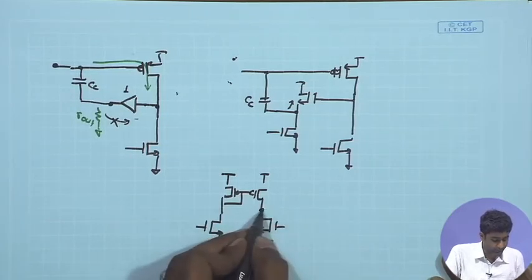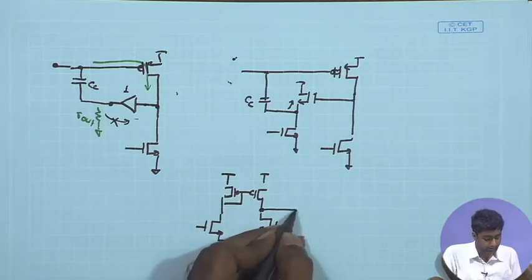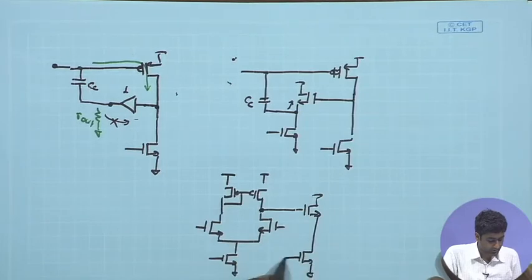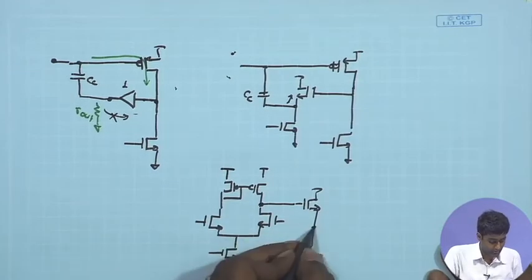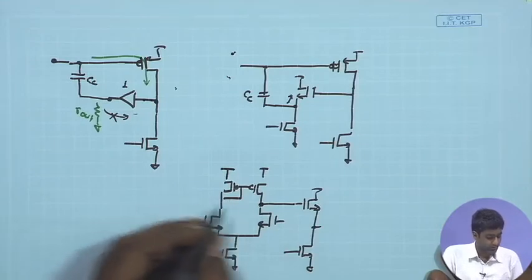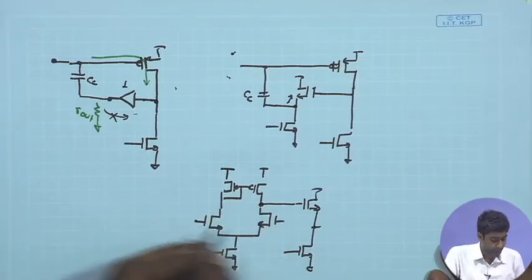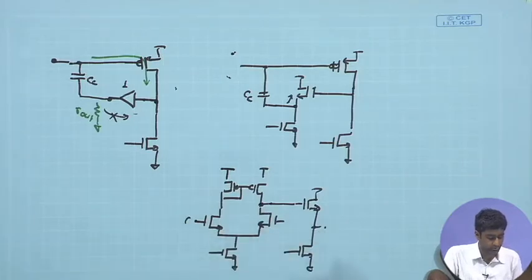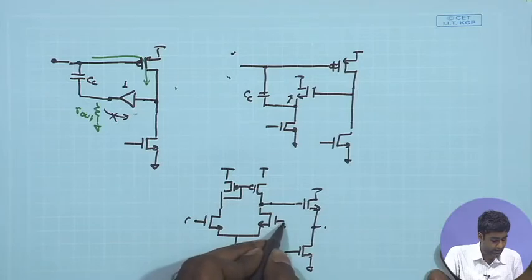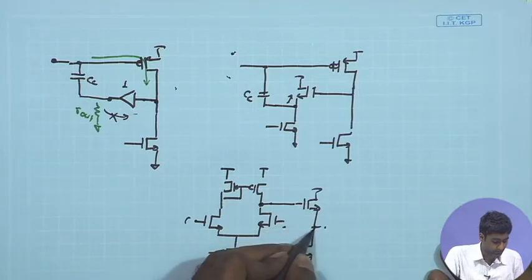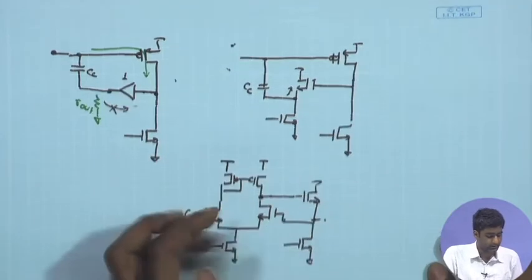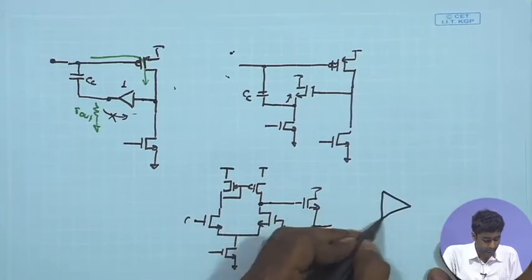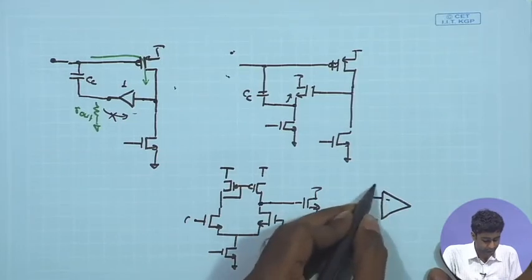And all the better if we apply another common drain stage after this, then you basically have a positive output over here. With respect to that, if you increase this particular signal, the output goes high and the final output goes high, and there is the negative output over here, and therefore I can connect these two. You can have the negative feedback over here, and as a result we know that for this particular circuit, the overall impedance for the voltage follower is going to be small.